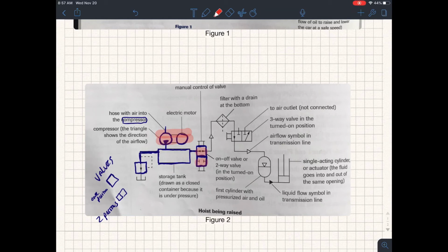And in particular, we've got this thingy right here that indicates, at the start of a cycle or the end of a cycle, what the state of the valve is. Not things that we need to understand, but I want to introduce the concept to you as well. So here we have our first valve. As you can read from the schematic, it's got two possible positions, and this particular valve has two ports. And you can recognize those two possible positions because on the schematic it has two of these squares.